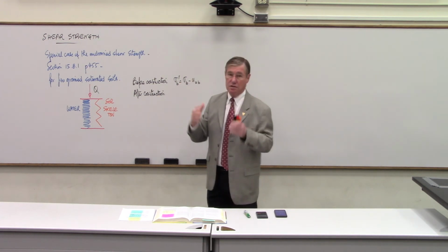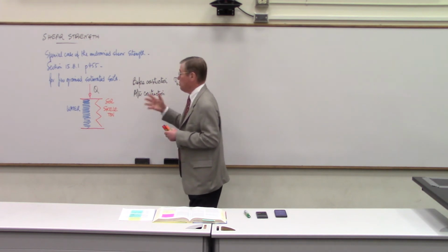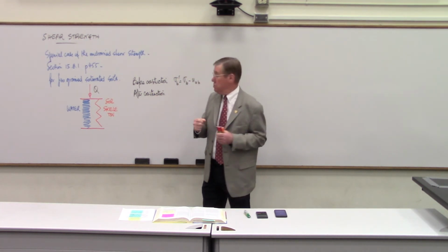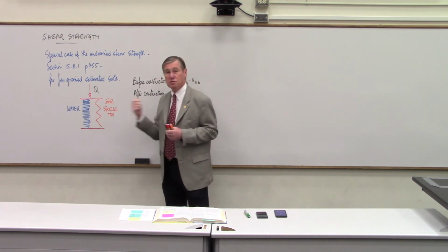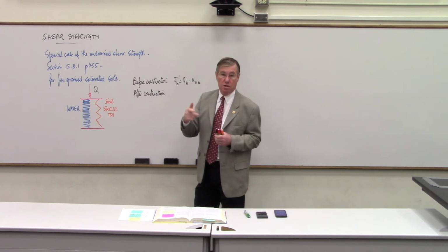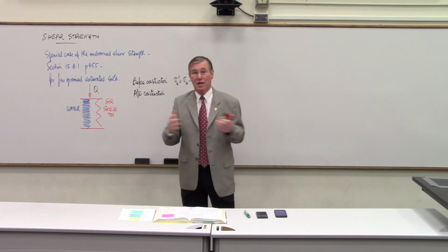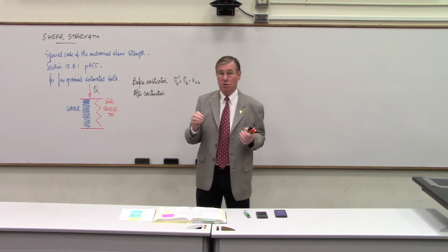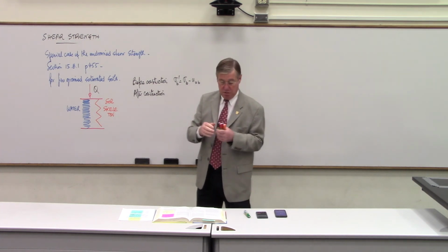So essentially this load that comes on the soil loads the water, it goes into compression, and the blue spring catches all the load. At the beginning, the load is carried by the water. Now that might seem a bit surprising, but the problem is that the water cannot escape from those small pores, and that's why it's an undrained behavior, and the water carries the load.